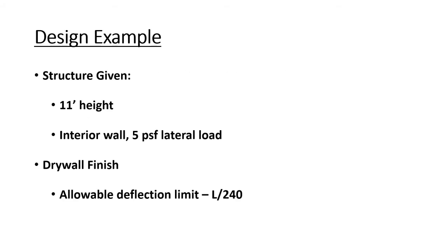So for our design example, we have the givens. The wall has a height of 11 feet. It is an interior wall and therefore subject only to a 5 psf lateral load. And since it is drywall with a paint finish, we will limit deflection to L over 240.